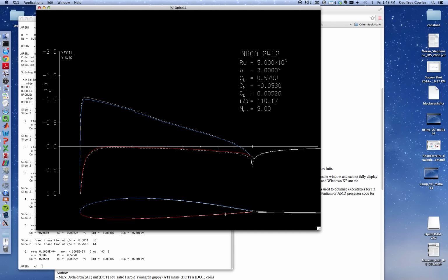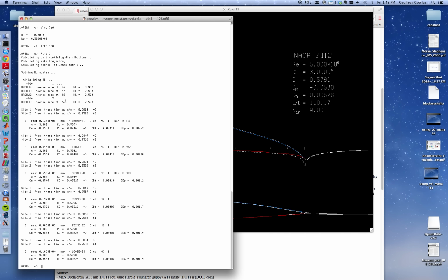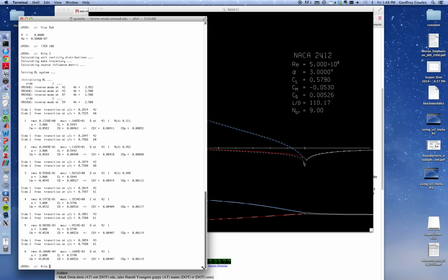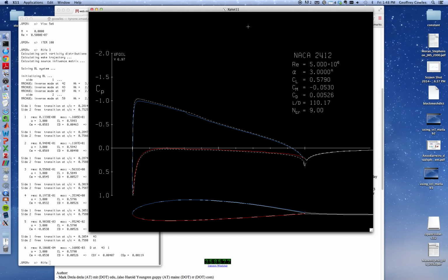The airfoil is not shown at an angle of attack. Even if we increase the angle of attack, the airfoil itself will still look like this, but the pressure distribution will change. Let's go ahead and do that. So I'm going to put alpha to, let me make this window a little smaller, so hopefully it will just refresh this and you can see both.